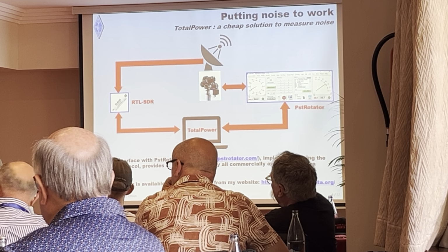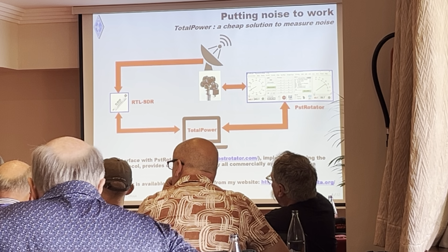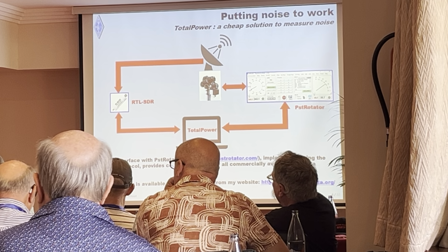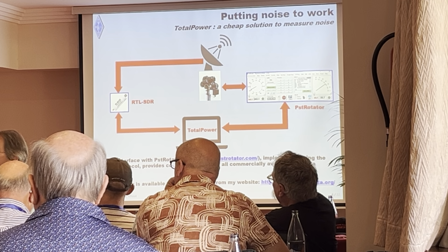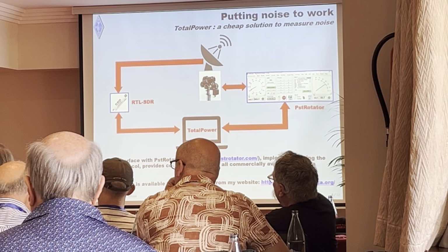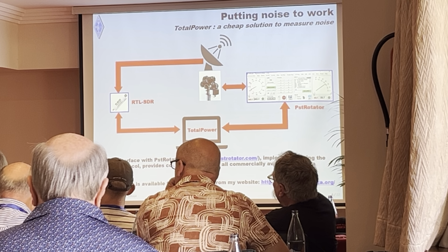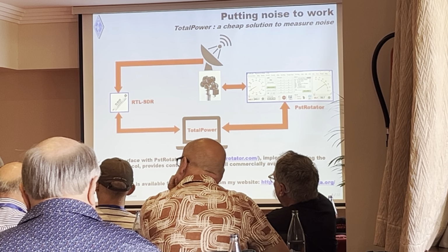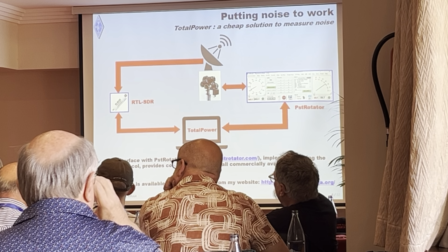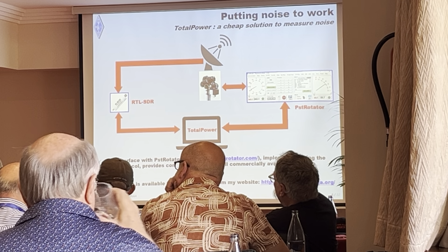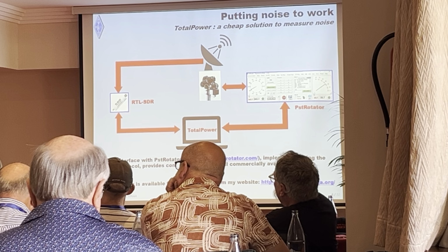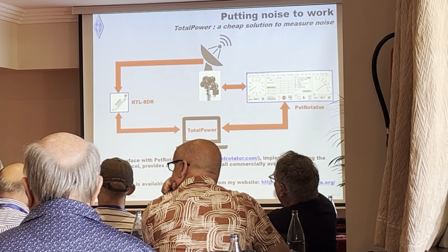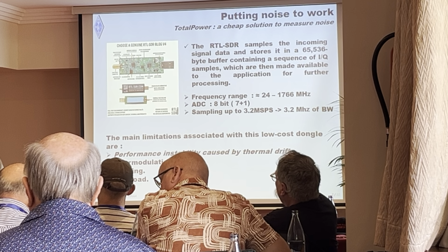The system is not calibrated. To calibrate this, I would need reference noise sources and put the correction inside. However, when we make measurements, we don't really need calibration. We need stability, because we make a comparison between one value and the other. So it's the dynamic range that takes care of it. This thing has 25, 30 dB of dynamic range, more than that.